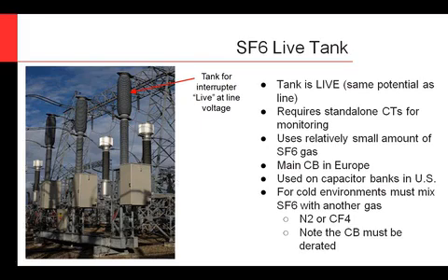And as I mentioned with the dead tank circuit breakers, you can actually put a heater on the tank itself, whereas these you cannot, so you have to mix it with either a nitrogen or a CF4. And if you do that, the circuit breaker must be derated. And this is to actually keep the SF6 gas from condensing in cold environments.